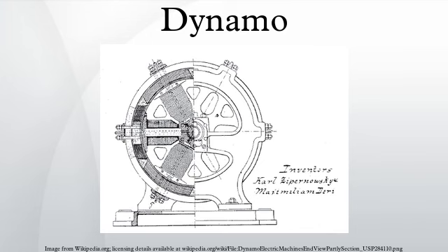The rotary converter can directly convert, internally, any type of electric power into any other. This includes converting between direct current and alternating current, three-phase and single-phase power, 25 Hz AC and 60 Hz AC, or many different output voltages at the same time. The size and mass of the rotor was made large so that the rotor would act as a flywheel to help smooth out any sudden surges or dropouts in the applied power.